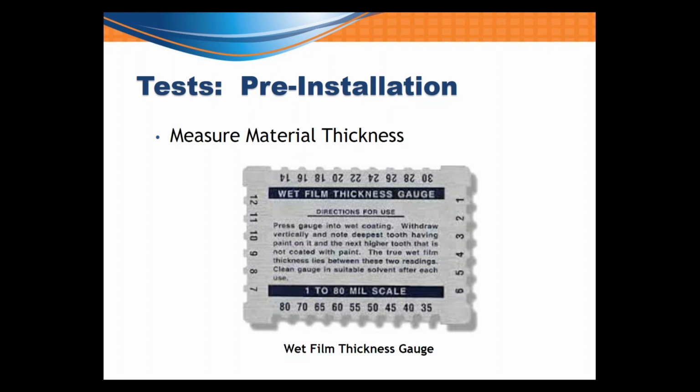To measure wet film thickness, press the edge of the gauge vertically into the wet material. Withdraw the gauge and note the deepest tooth with material on it and the next higher tooth that is not coated with material. The wet film thickness lies between these two readings.